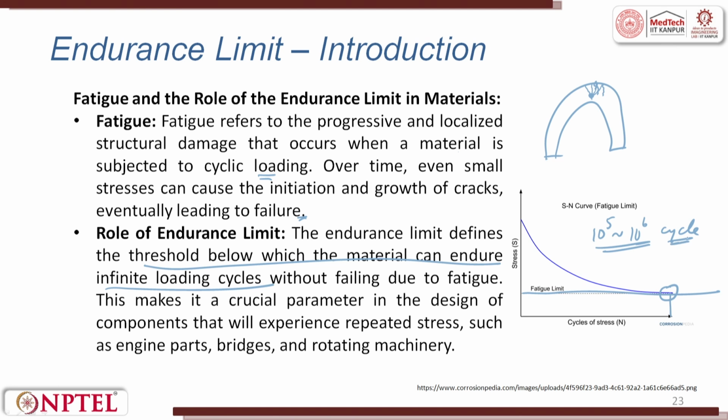The role of endurance limit: the endurance limit defines the threshold below which the material can endure infinite loading cycles without failing due to fatigue. This makes it a crucial parameter in designing a component that experiences repetitive stress. It can be an engine part, a bridge, or a rotating machinery.